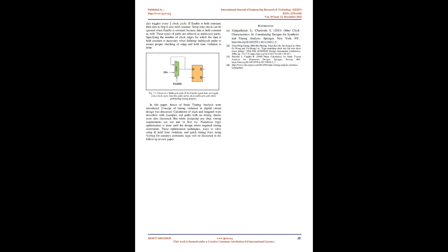Another example is that of a synchronizer that is used while doing clock domain crossing. The first flop in the synchronizer circuit may or may not enter a metastable state. Input setup and hold time, TSU and THD, can be affected by the clock period, TCLK, and different delays in the design such as clock skew, clock-to-Q delay, TCLKQ, and logic delay between the flops. In addition to different delays, clock latency and clock jitter will shift the clock edge from the ideal position, and hence these uncertainties will also affect the setup and hold time constraints of the flop.